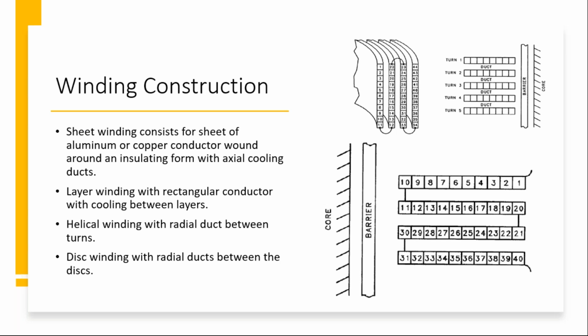Going to the other types of winding, there is helical, which takes multiple winding conductors together and winds them in a helix form. And the last one is disc winding. In these two windings the conductor is supported face to face and separated by spaces in between, which provide very good strength against the axial and radial forces in the transformer during short circuit.